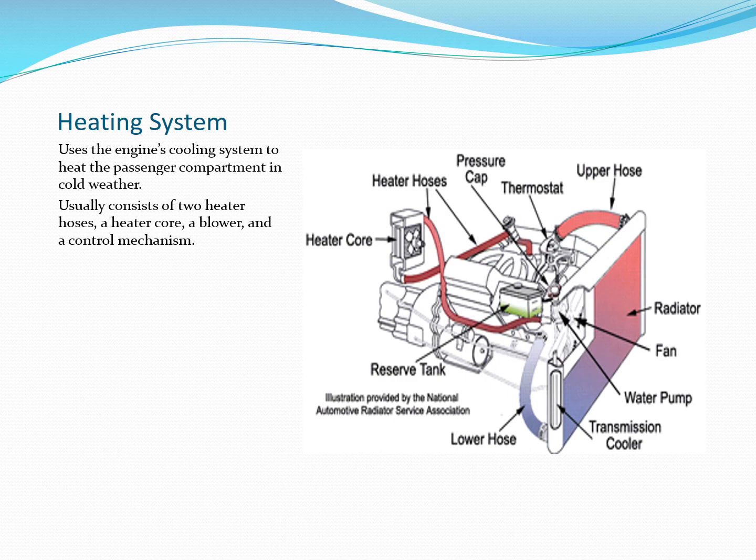The heater core is located inside that box that we looked at before. It's in the same box that the air conditioning evaporator is in, and the blend doors control the airflow either over the evaporator, over the heater core, or over both. We can run air over both. We might run air over the evaporator to mix with the heater core air to dehumidify the air during wintertime, or we might run air over the heater core during the summertime. So these systems work together in that plastic box underneath the dashboard or behind the glove box.